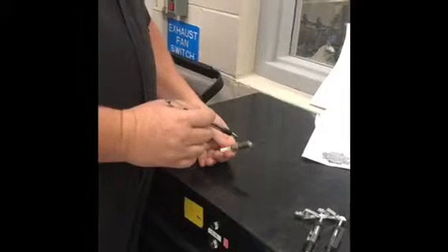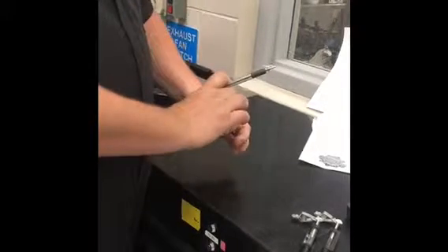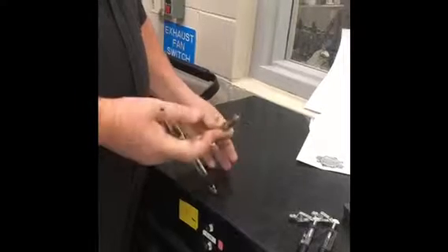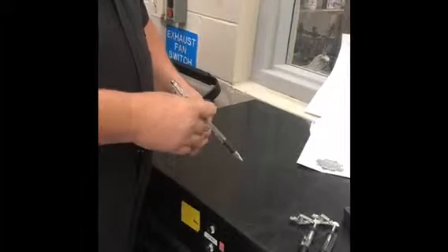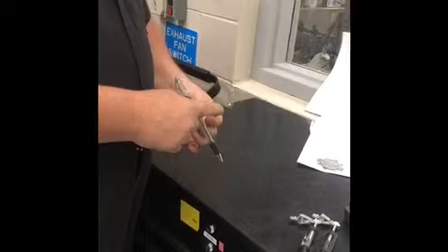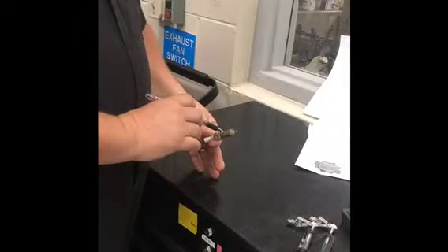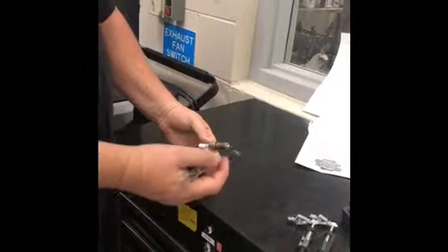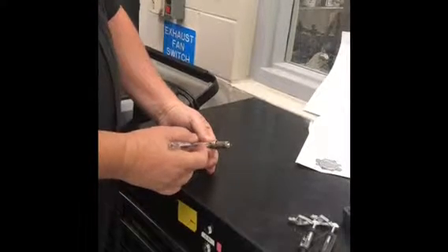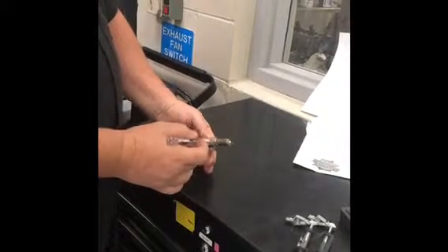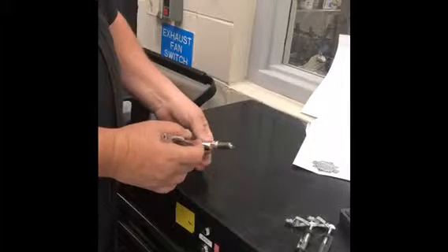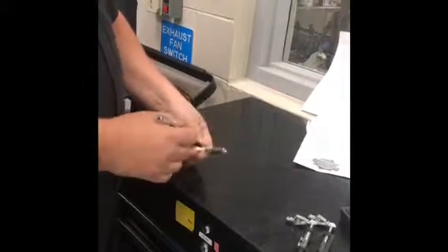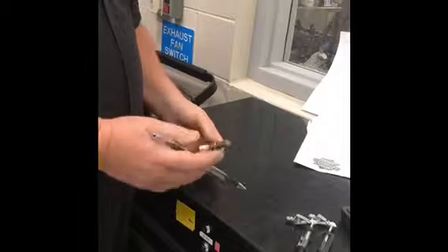All right, now we're going to go over some terms to do with spark plug. First one will be the thread size. The thread size is basically the diameter of the threads on the spark plug. Now today, most light duty vehicles, they use a 14 or an 18 millimeter. The next thing we'll talk about on the plug is the reach. The reach is the distance that the plug will screw into the chamber. Heat range, next one's a heat range.